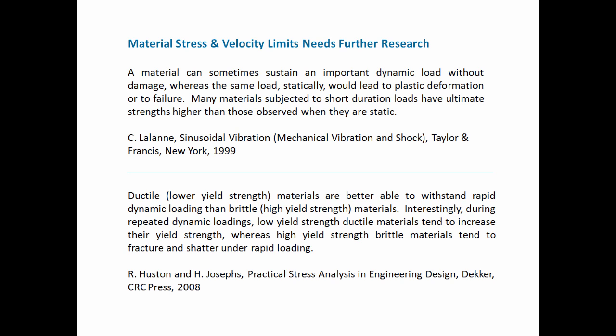Here's another quote. Ductile, lower yield strength materials are better able to withstand rapid dynamic loading than brittle, high strength materials. Interestingly, during repeated dynamic loadings, low yield strength ductile materials tend to increase their yield strength, whereas high yield strength brittle materials tend to fracture and shatter under rapid loading. That's from Huston and Joseph. So I think that's getting into some of the strain hardening type